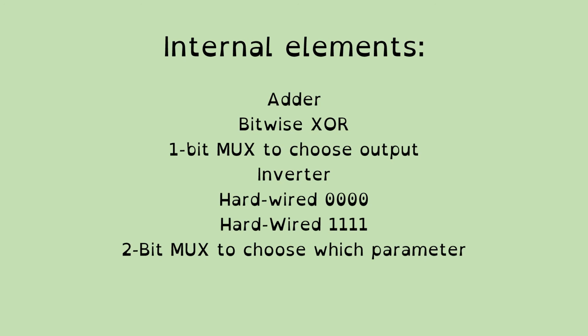Where I have inputs, I'm not going to. And this has worked for me as a general principle, so I'm going to stick with it with the ALU. Basically, you don't want to do both just in case one's feeding directly into another and you end up duplicating too many registers. But also, if you actually internalize the registers into the pieces of hardware, it makes more and more of your elements look like bus-ready pieces of hardware, so you can just connect them directly to the bus.